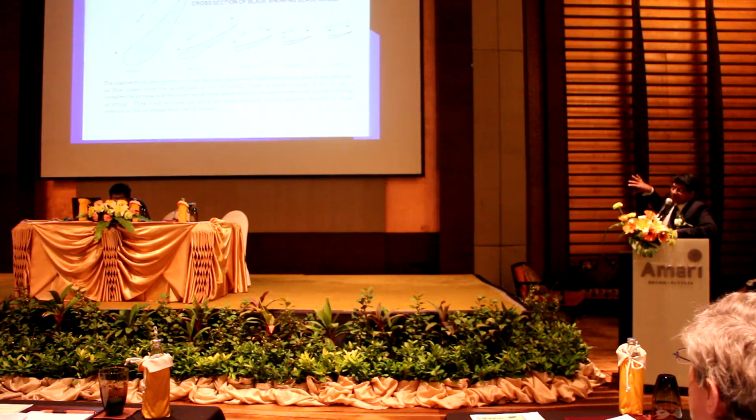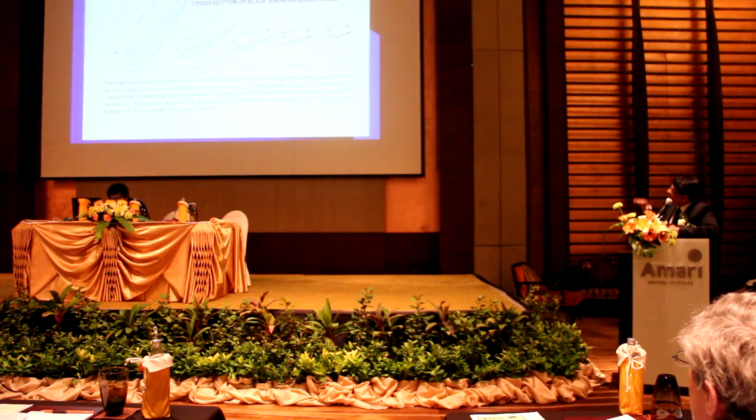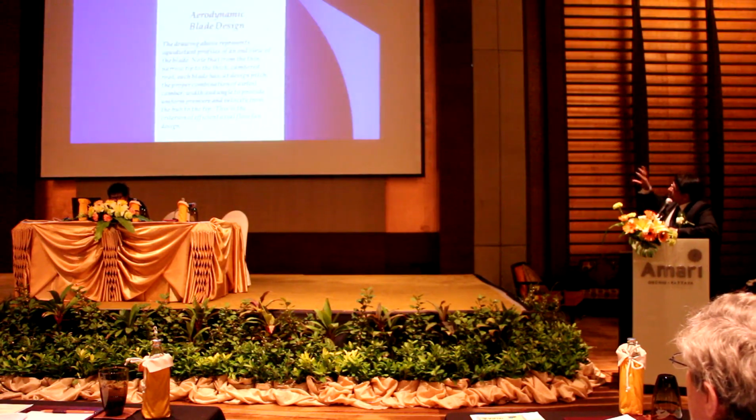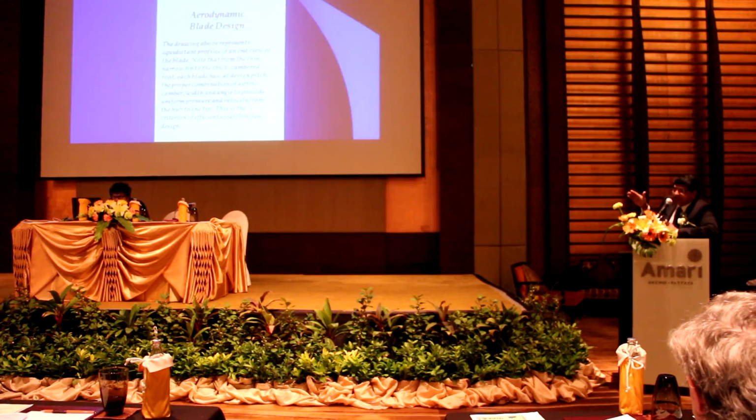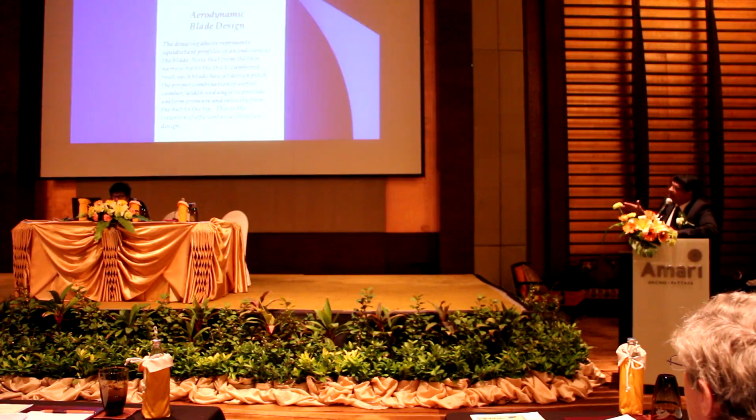This is giving a cross-sectional detail of the blade, showing the blade angles at various locations from the tip on the right extreme to the shoulder, where you have the maximum aerofoil, and you can see them twisted physically. This is one view from the tip of the blade to the shoulder of the blade, how these aerofoils will look. At the tip you need a smaller aerofoil, at the shoulder you need a bigger aerofoil.